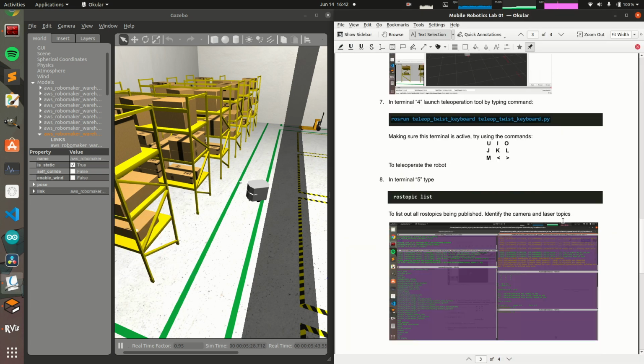Okay, so now that you can control the robot, what we're going to do is, you learned in the introduction to Ros section that all the information coming from the sensors or the motors is communicated to each other using something called a Ros topic. Remember, we learned about different Ros nodes, and information is transmitted between these Ros nodes using Ros topics.